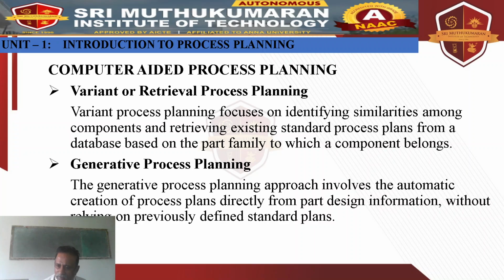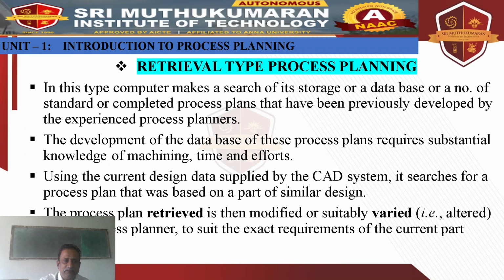They get the design information, they start working on the process plan, without relying on the previously defined standard plans. So, retrieval or variant type process planning. In this type, the computer makes a search of its storage, that is the database, of a number of standard or completed process plans that had been previously developed by the experienced process planners.